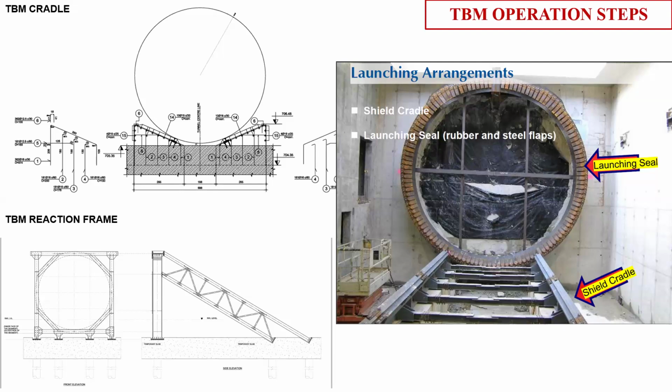Maybe some gantry foundation they have to prepare. The gantry is mostly for the lowering of your TBM and lowering of your segments. But if you are preparing a shaft, you need a gantry because the gantry will move over the shaft. But as I told you earlier, in the Pune Metro we did not prepare any shaft. We directly launched from the open ground. The open ground where we launched the TBM is the interface between the elevated and the underground, so we launched the TBM directly from there.